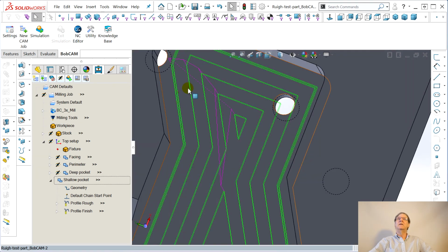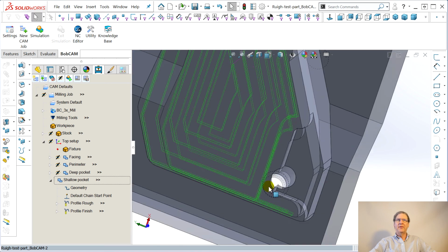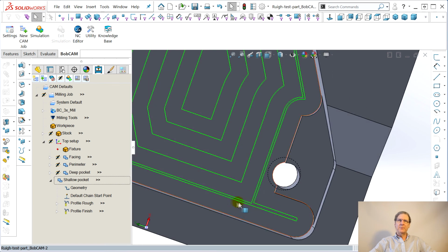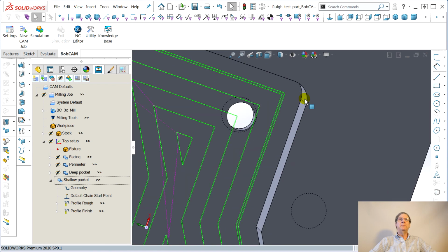And you see how it's done the toolpath straight across here, so the top part, and straight across here. When it does the finish pass with no stock allowance, leaving a little meat on the sides that the rough pass does, it can go through and get this little pocket because it's 0.26. Dave is a genius. He didn't make the diameters of all these fillets 0.25. That means the tool has to stop at that point in space and then change direction. He made them 0.26 diameter. So a 0.25 quarter-inch end mill will actually sweep around a little arc like this. How cool. And then you see the same thing here in the finish pass.